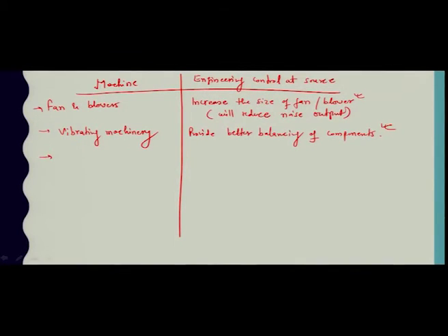For impact equipment, such as stamping or forge hammers used in manufacturing industries, we have to move the equipment onto rubber mounts to reduce the transmission, if possible.